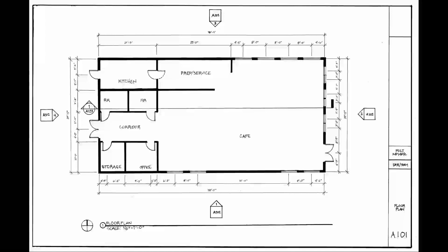There are other ways of drawing a section tag so that it might continue through here, create a vertical line and move up, and it can be a little bit of a zigzag, but that can get confusing. So for right now, we just want to keep the section tag straight, with the idea that we're cutting through and seeing everything that we would see if we looked that way. So now that we understand a little bit more about this section tag, we're going to take a look over to an actual section drawing.